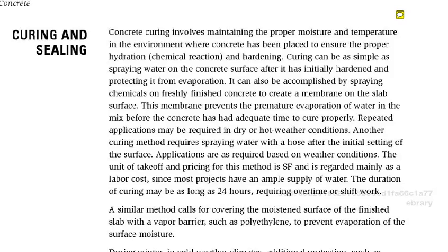You have to also cure and seal concrete. Generally, you're going to cure it, or depending on the material you use, there are curers and sealers together. But for flat work, generally you're going to apply a curing compound, and you're going to put that on after the concrete's been finished and it's been allowed to set up slightly.